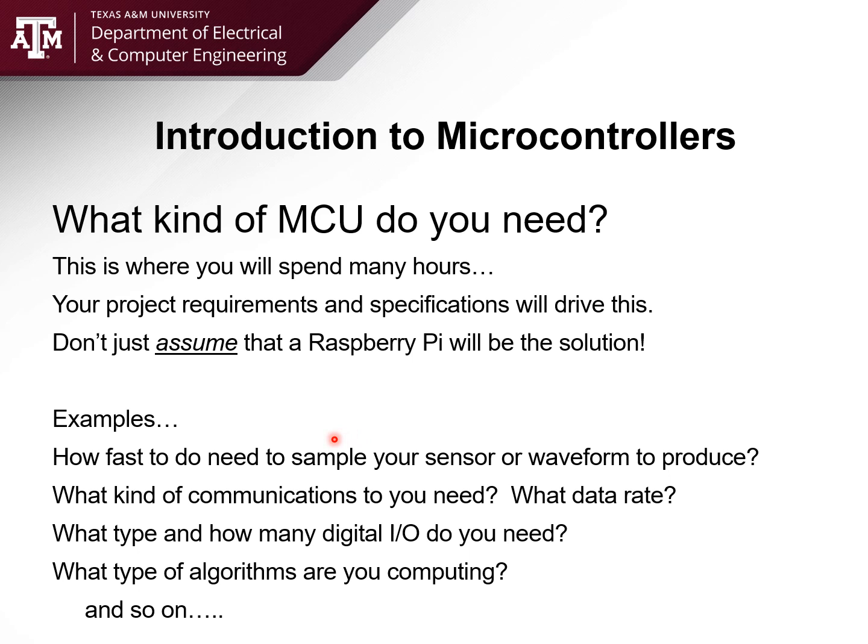However, if you're trying to do image processing and use a camera, and you're using a high-speed camera, like you're working on, say, an assembly line, and you're building the mechanical system to actually drive an assembly line that's running at full speed, you're probably going to need a high-speed camera that's running at 800 frames per second. In which case, it means your microcontroller, to make intelligent decisions and do the image processing, needs to be able to receive 800 frames per second. If you ever do the computation on how many pixels per second that is, that's a lot. And so your average microcontroller probably will not do that.